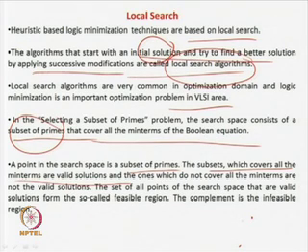But as we are defining what local search is, we are trying to correlate the local search heuristic with the previous lectures. Corresponding to the last three lectures, if you are given the prime implicants for a function and want to find a subset of prime implicants, you are not taking the branch and bound algorithm, you are directly going for a heuristic. In this case we can say that local search is a good heuristic. You take an arbitrary set of prime implicants, that is a solution. A subset of prime implicants is a solution, and it can be valid or invalid.